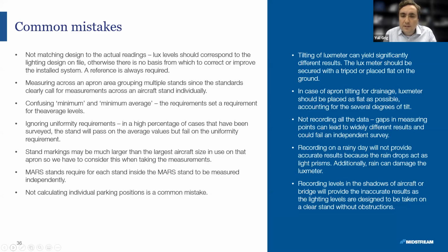Then we've got some others here. Tilting of the lux meter. If you hold the lux meter in your hand, as opposed to laying it flat on the ground, any degrees of tilt can give wildly different results, which is significant. So the lux meter should always be secured either with a tripod or placed flat on the ground and left there to stabilize for a few seconds. There are instances where you have apron tilting for drainage. That's been asked before, and it can be up to 1 degree. The lux meter should be placed as flat as possible, accounting for that several degrees of tilt.